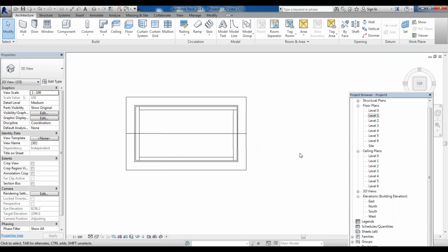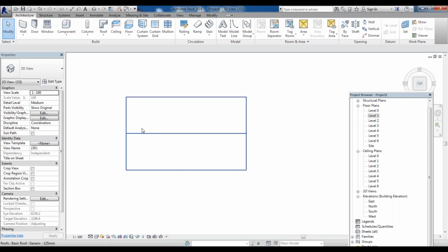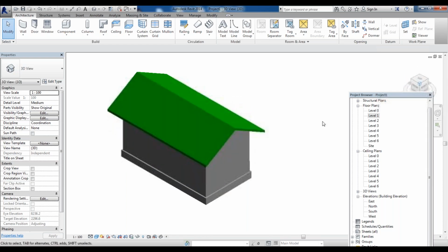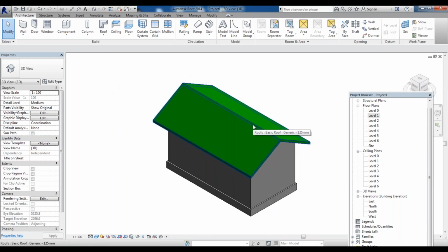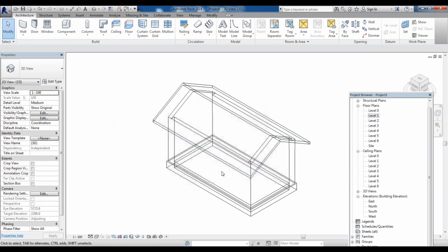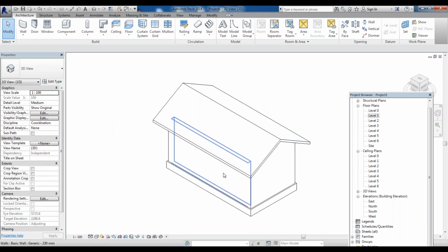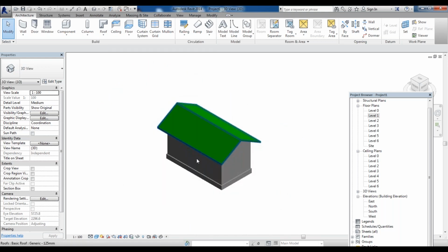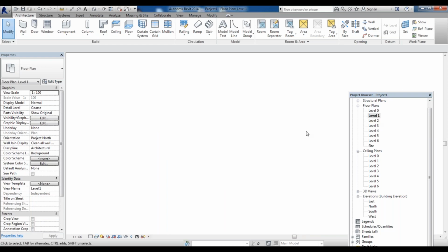Do you remember this command? This is WF for wireframe, HL for hidden line, where inside lines are not seen. Excuse me for that. And SD for shaded. So this is shaded. WF for wireframe, you'll see the inside line. HL for hidden line. SD for shaded. These are very important. You have to view them, use them appropriately. Okay, go to the level 1 again.